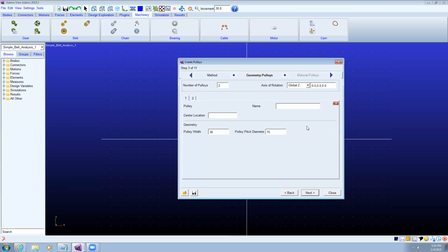So here the name, first one is the driver. So we know the driver for the belt system. Now he's defining the central location. Now I can just push back my pulleys to the center distances. I can say in the coordinate 150, 0, 0.